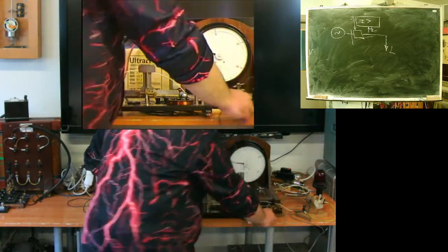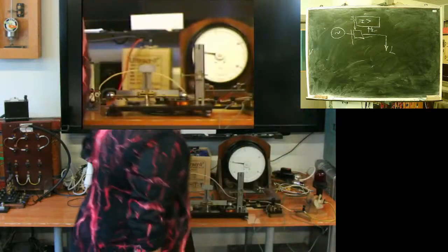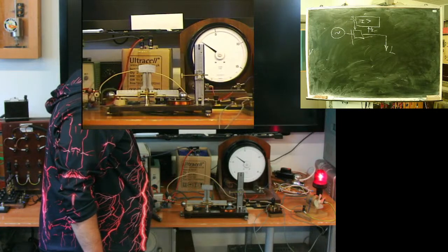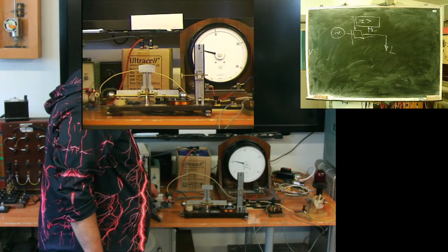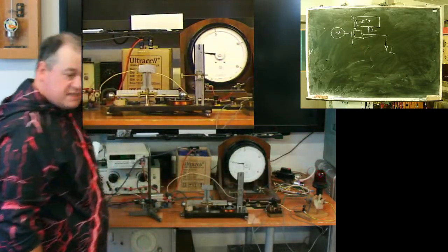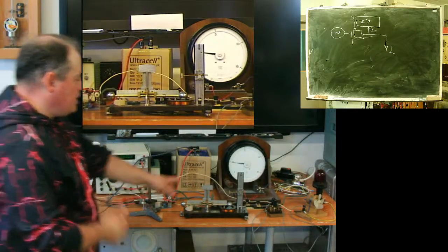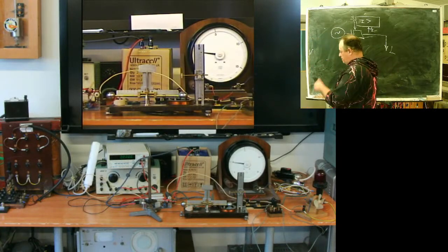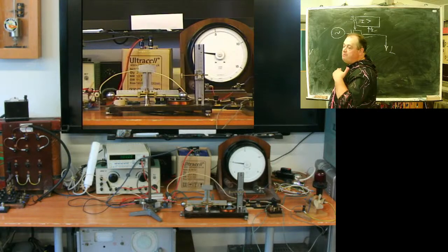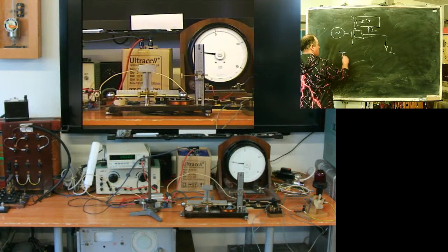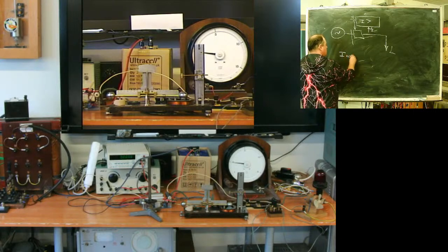What happens if I reduce the load? We can live with this. But my relay trips on the full load. This is my first mistake. I set the trip current below the maximum load current.